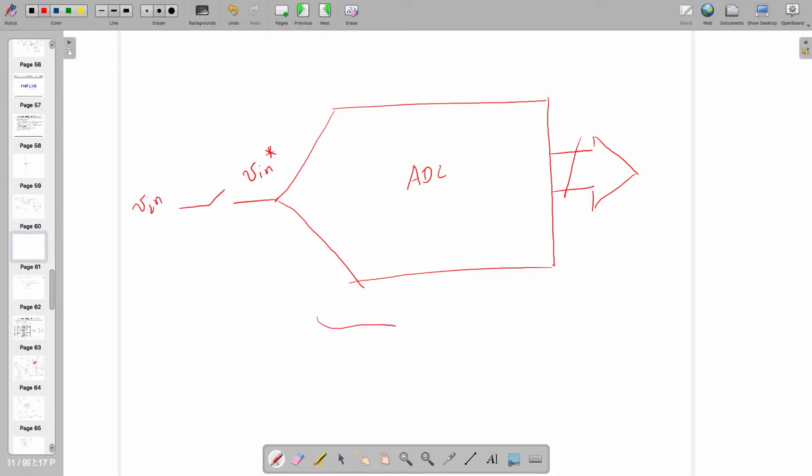So whatever the conversion time needed here, one extra clock cycle is needed because of the switch. So as many switches as you add in a path, that many extra T clock you need. So do not add many switches if not required.